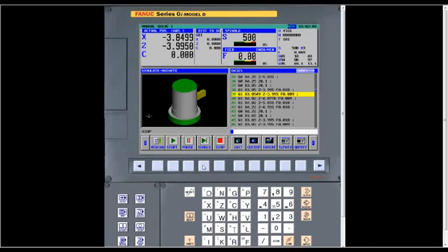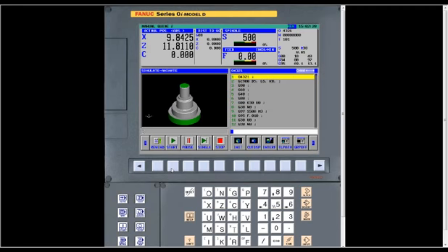It does a rough cut, another rough cut. I'm seeing it showing the tool, and I'm showing it like it would be on a VTL type machine. That's how I got it configured right now. See, it's going all the way through and cutting the entire part. I'm just going block by block at this point. Then if I press start, it'll do it much faster.